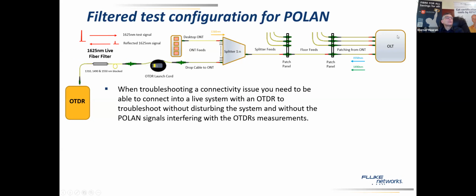So you have your OLT, it sends light on the fiber. You have different splitters along the way, let's say. Here is a 1-to-N splitter, and you go down to the ONT, to the user. Now you want to test with your OTDR upstream. Remember, downstream testing is a little bit challenging because of all these fibers. The OTDR will not know whether this light is coming from one fiber, connectors, or different fibers. So if you measure upstream,